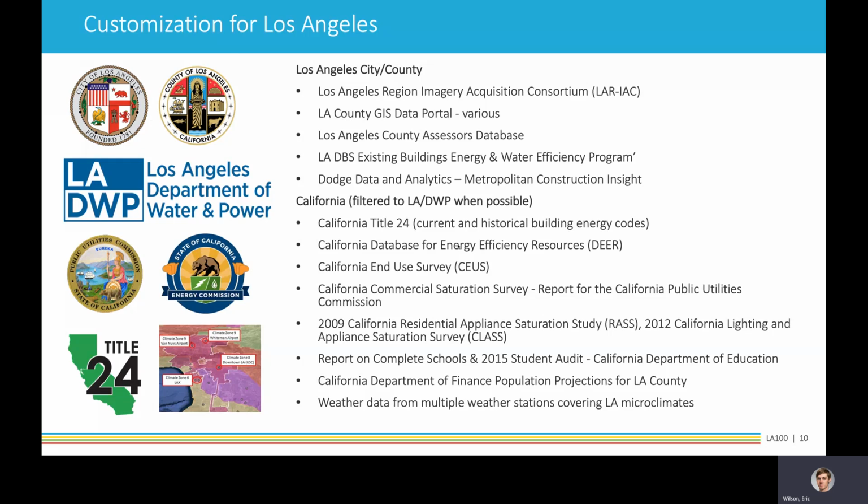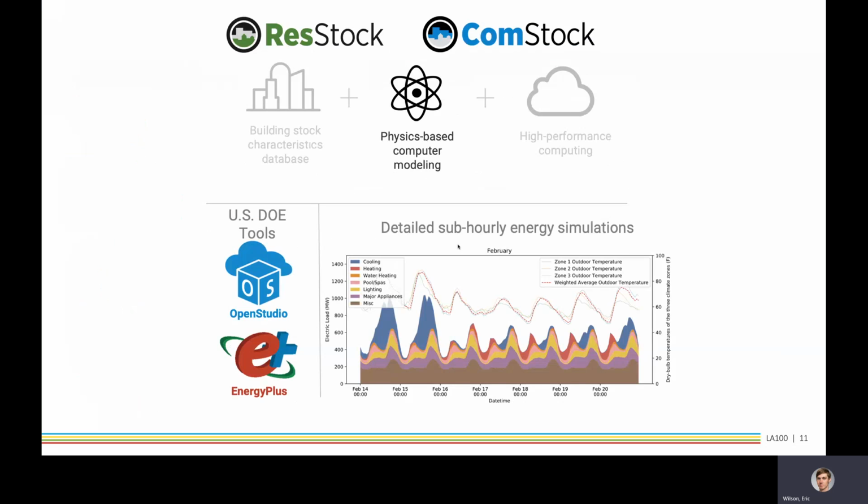So second, the physics-based computer modeling. For this work, we used the OpenStudio software development kit and the EnergyPlus simulation engine for sub-hourly building energy simulation. This allows us to look at what-if scenarios about different technologies being deployed, even if those technologies don't exist in the stock today.